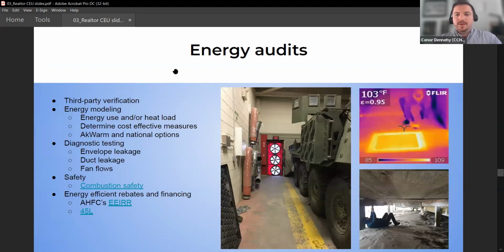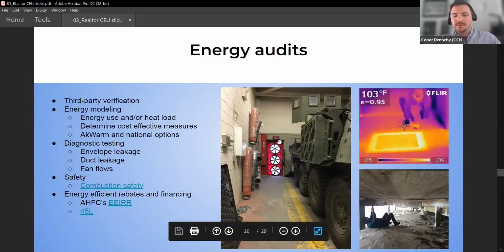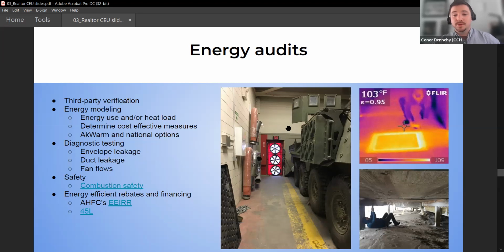And so if you're not familiar with energy audits in general, this is a couple pictures that show what an energy auditor would do. This is obviously on a larger location than a house. So people will put blower doors through the front door of the house, and with a single fan, you won't need as many for a residential setting. They can essentially figure out exactly how much air is leaking through the house's envelope.